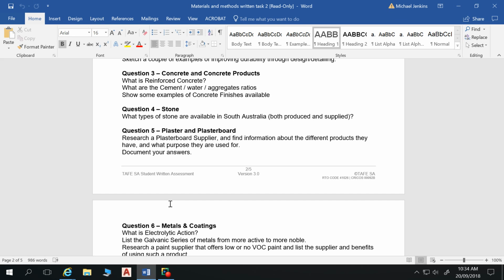If I'm filling up the whole wall all at once, I'll want a really runny concrete mix, a concrete mix with a high slump. That's when I tip it out, it goes like this. That's because I don't want air bubbles in there. I want it all to mix in. But I'll be sacrificing strength in that.